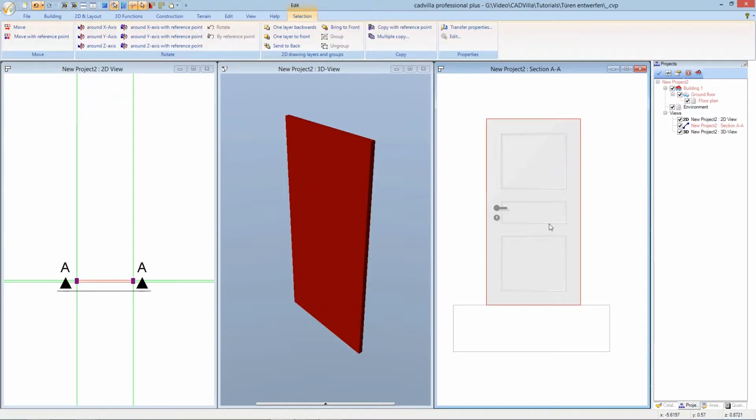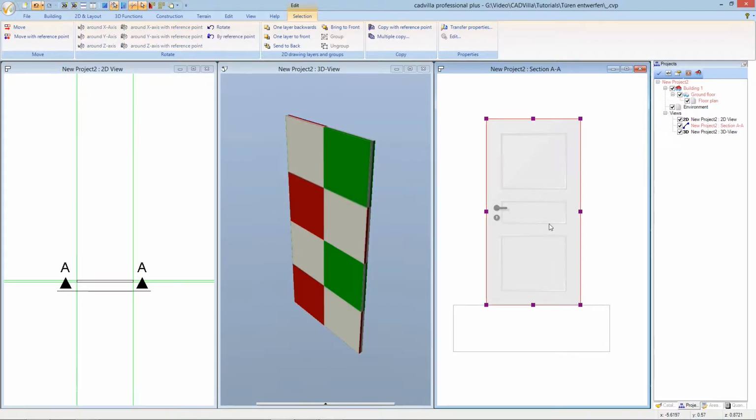We select the picture. If you can't select it the first time, don't move your mouse and make again a left mouse click. Press the right mouse button and select Adjust Scaling. We select 2 points of known length.